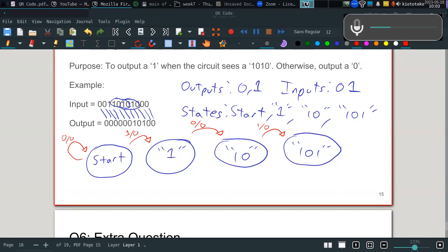And here is where it may start getting challenging, but let's review what happens here. If we're in a 1 0 1, let's assume here. If we get a 0 here, that means we would output a 1, but where should we connect this to have this behavior? Again, if we get a 0 here, that means we are detecting this sequence and we should output a 1, but which other state should we connect this state to in order to continue detecting these patterns?